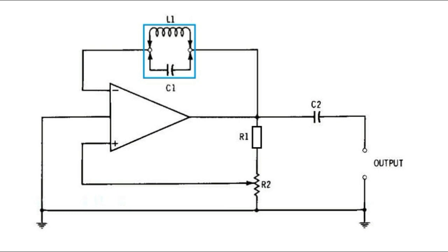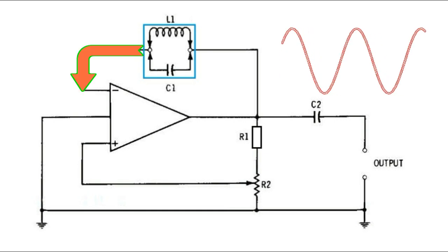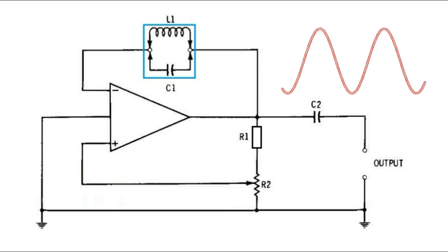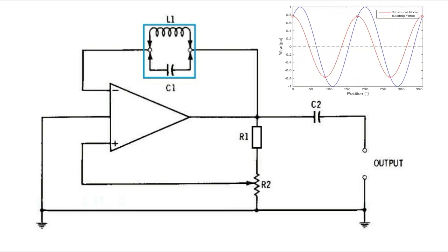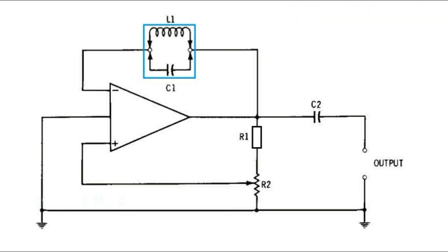In this op-amp oscillator setup, the positive and negative feedback are used both together. The tuned circuit built using the L1, C1 part connected in the negative feedback loop decides the oscillation frequency of the circuit. Since the L1, C1 works like a wave trap, this tuned stage of the circuit eliminates its resonant frequency, FR, from the feedback loop. The op-amp consequently behaves like a sharply tuned amplifier, becoming responsible for transmitting the frequency FR. However, its gain gets terminated at all other frequencies.